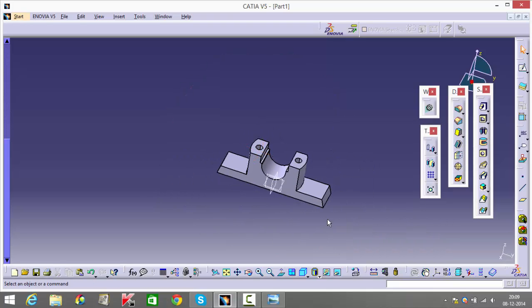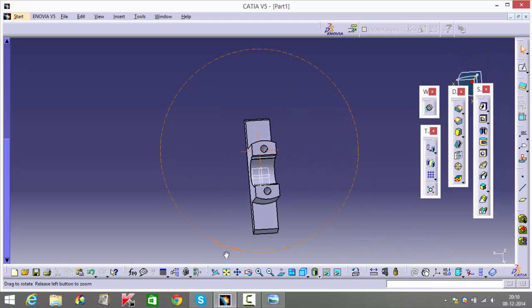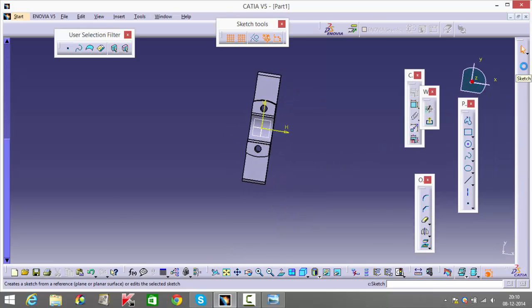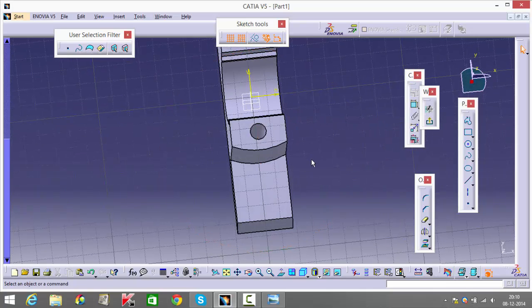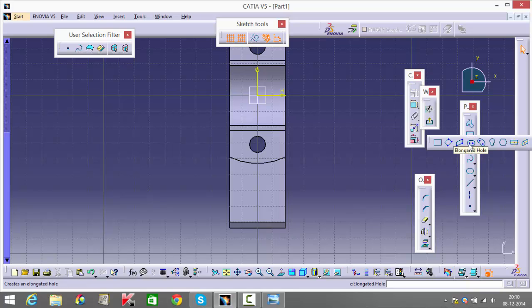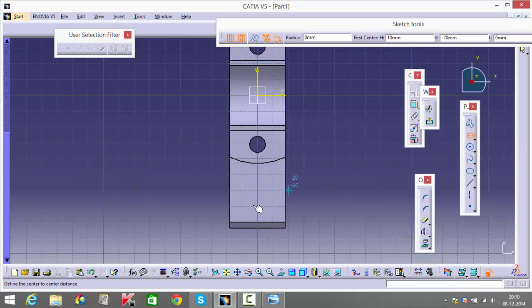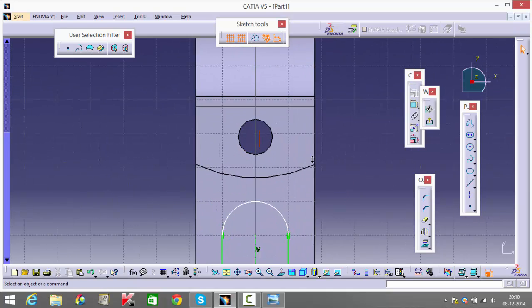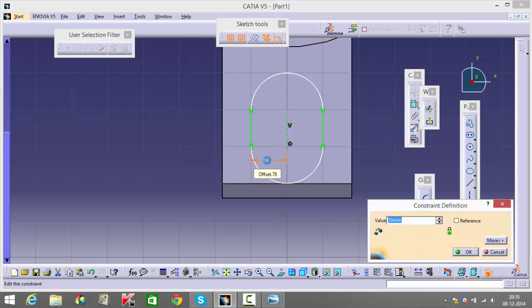After we've got this, we have two, you could say, elliptical kind of pockets over here. We have a predefined function. Elongated hole is what it's called. We're going to select that and try to get it on this axis itself and make a small, just push it, make a small straight line and move your mouse away from it and you'll get this. Once you get this, you need to change this radius. The radius that's given to us is 5, so we're going to make this 5.